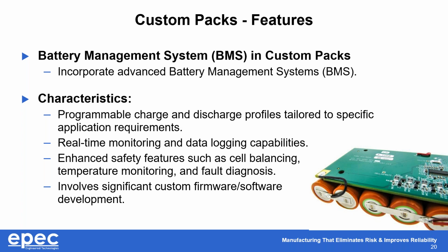So when we talk about the BMS on the standard pack, it was simple. We talked about temperature, fixed charge, and discharge, and that was really all we're managing there, but not in a custom pack. Here we do internal cell balancing, fault diagnostics, and charge and discharge profiles that are not only tailored, but inside tight tolerances that can be very specific. We can really fine-tune. I think there are anywhere between 10 and 20 different parameters that we can monitor, log, and adjust in the pack, to not only work for your application, but as it ages, it helps it last longer and actually manages your device better over time.